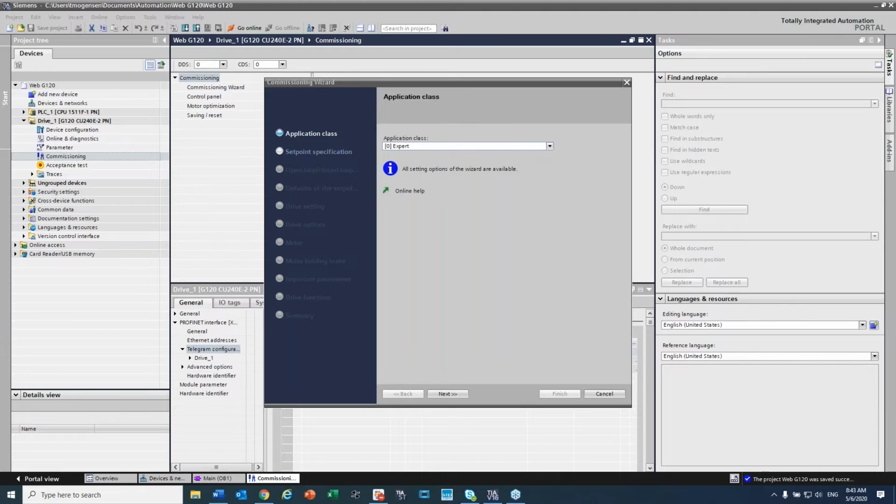But my question is, I missed the PLC part. Do you have to designate space, like an integer or floating point? Like, you need to designate address space in the PLC? I've done nothing with the PLC yet to give it a space or any addresses at all. The only thing I've done is I've let the PLC know, after I attached the drive to the PLC, that I want to talk to that drive with Telegram 352. Okay, like I said, I want to make sure that I didn't miss anything, that's all. Nope, I just put the drive in there and I said it's going to talk with Telegram 352. And when I told it to connect to the PLC, they've now linked together in the fact that that will be Telegram 352 and it will deal with it for what we're doing. Okay, thank you. Sure.